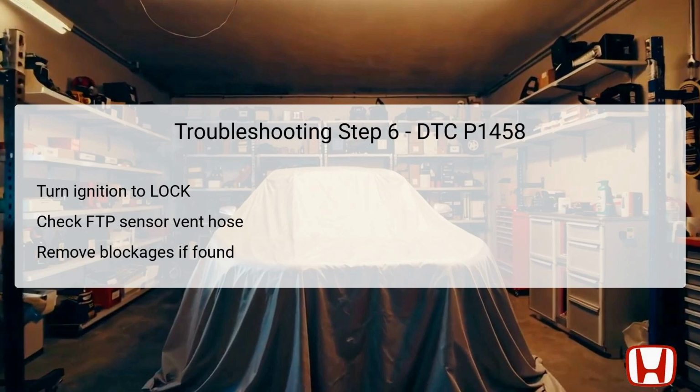Once again, utilize the HDS to monitor whether the measured pressure values hover around the specific thresholds of 0.67 kilopascal or greater, or negative 0.67 kilopascal or less. If yes, you will need to remove any detected blockages in the FTP sensor vent hose and consider replacing the hose itself if necessary. This step is vital to maintain the proper functionality and accuracy of the FTP sensor.